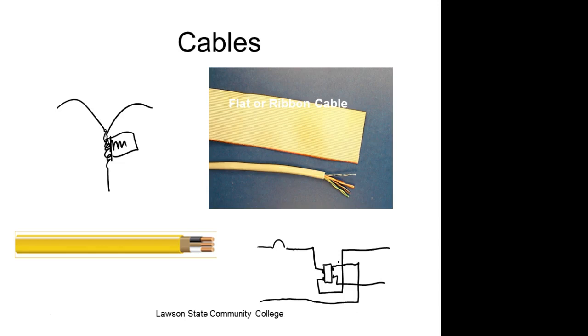The best way to do it would be this way right here, where you take your hot lead and twist it, but make a little pigtail, right? You understand that? And then get you some wire nuts for the right wire gauge and do the same thing on your neutral and the same thing on your ground. It's legal to loop the ground, by the way. It's not legal to loop a hot wire.